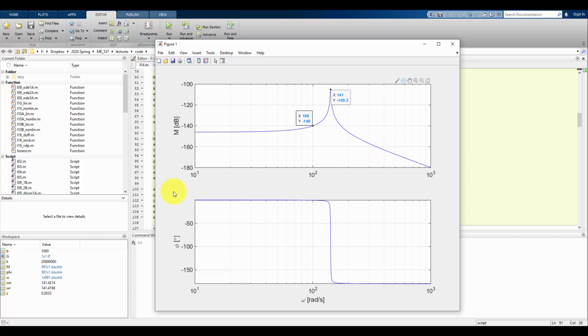And finally, maybe changing the damper would have changed things a little bit. We can shift this peak more to the left if we increase our damping, because the resonant frequency is going to drop relative to the natural frequency. But something like that might not be quite as effective as changing the M or the K. But we do have some options in redesigning our system if we must drive near the original natural frequency or resonant frequency of our system.